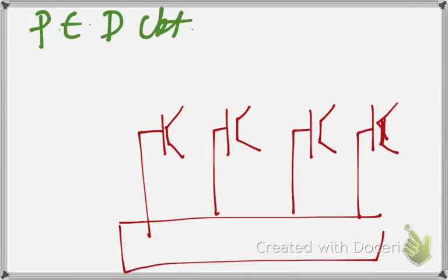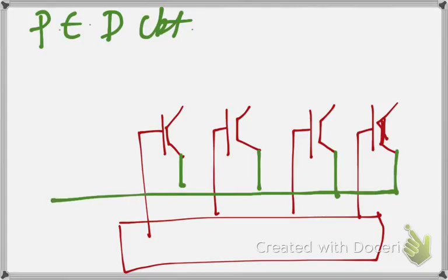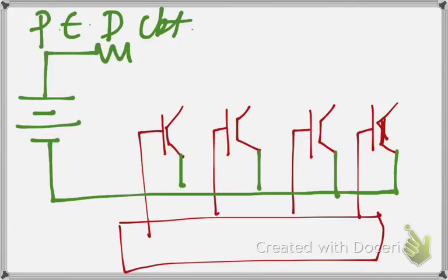It is from your controller that you'll be receiving the gating signals. And all the V plus of these transistors acting as switches are connected to a supply of about 12 volts through a series resistance. We will learn about the significance of the series resistance later in this video.